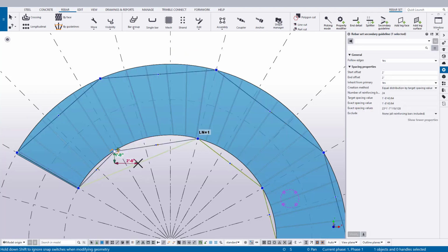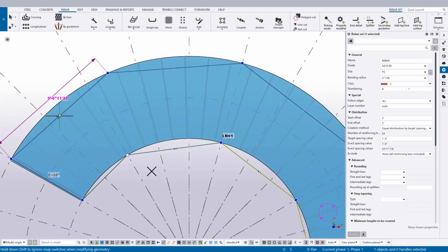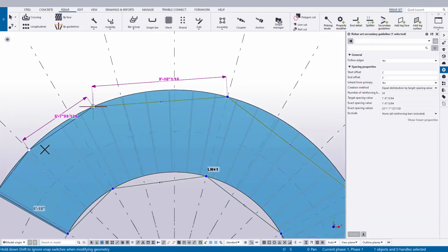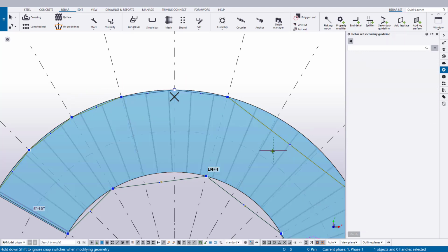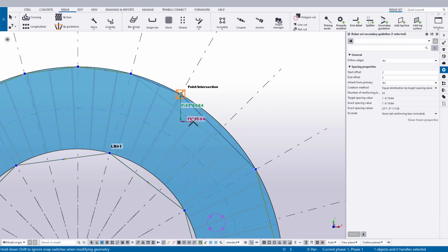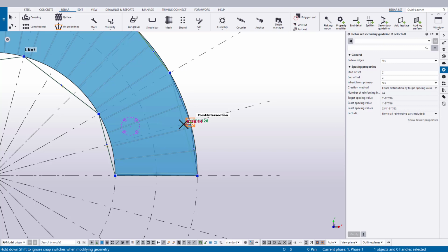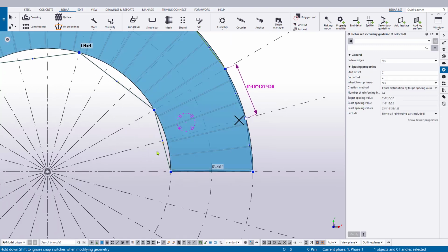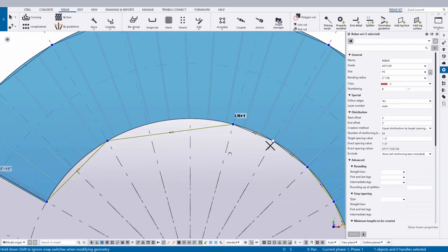So when it comes to interpreting and making sure that you have the best minimum and maximum spacing, as these will be different at either end of your ramp, I suggest creating points at each of your azimuths, which is where our grid will come in handy. This provides us with some fidelity and control and accuracy for the spacing of the bars. Make sure that you're just going ahead and dragging those center points, the round nodes there, and snapping to the edge of concrete where the radial azimuth meets.